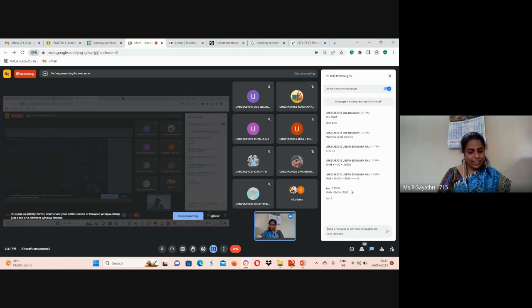Then we can solve the 2 equations. Use calculator mode, equation 1, 2 unknowns. A1 value 16, B1 value 4, C1 value minus 16,000, A2 value 4, B2 value 16, C2 value minus 15,030. MB value, MC value. Did you get the answer?